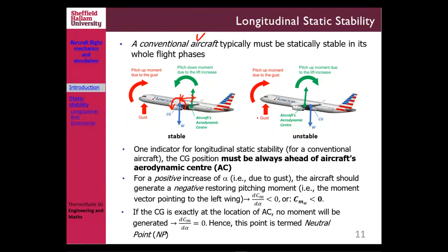Why? Again, back to the right-hand rule. The y-axis is positive towards the right wing of your aircraft, so the moment going toward the outside of the board is negative. Now, if the other condition applies, where your lift is slightly forward of the CG location, the pitching moment will make the aircraft pitch in the opposite direction.